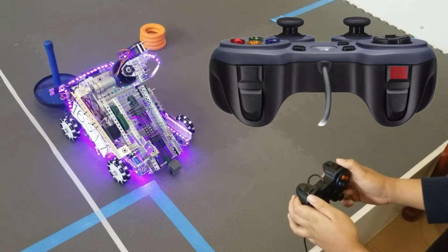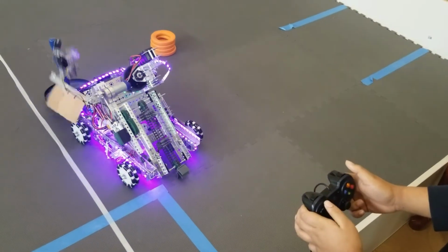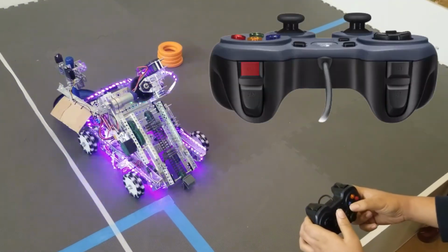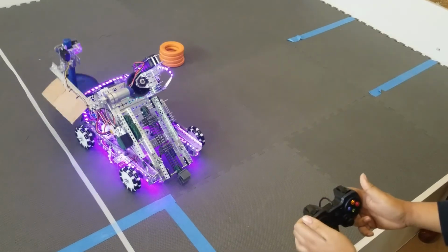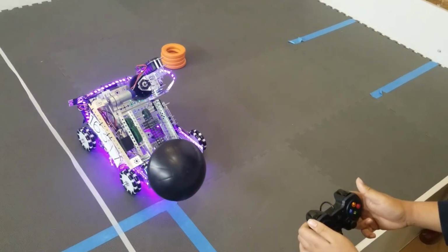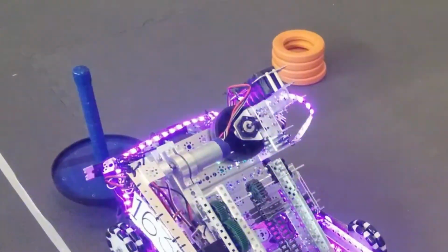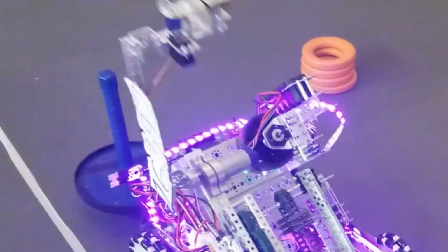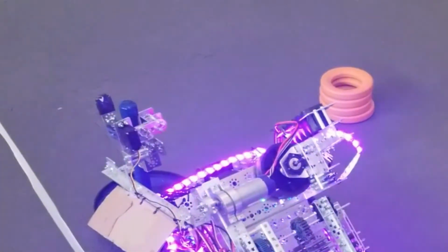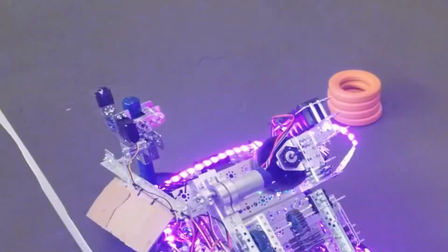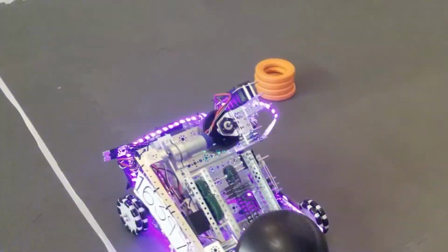Another small but useful automation is that the arm has a toggle for extending and retracting at wall height, which uses predetermined encoder positions so that the driver only needs to press one button for the arm to accurately and quickly go to any of the 3 spots. Additionally, the wobble goal gate mounted at the end of the arm also automatically opens and closes depending on the position of the arm, so it can either pick up, hold, or drop the wobble goal.